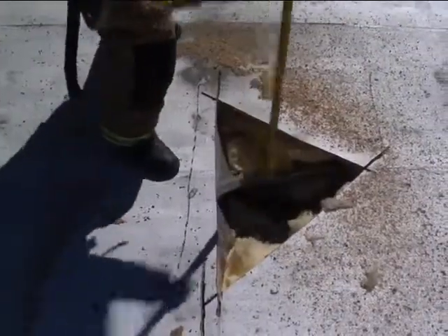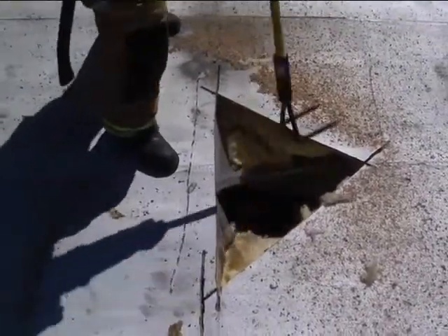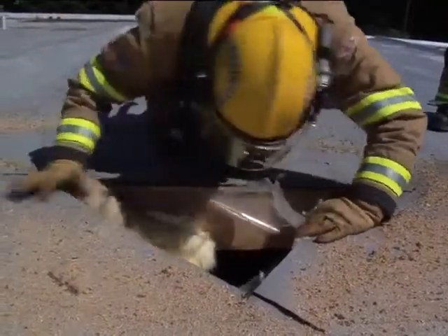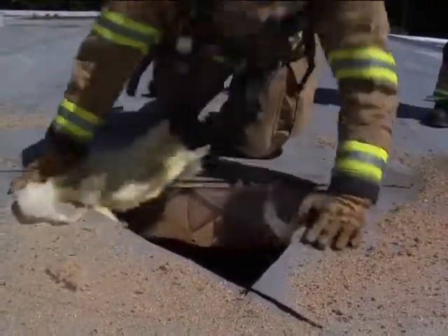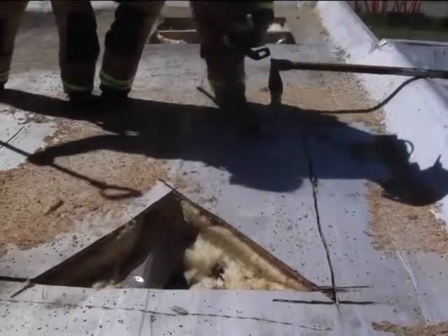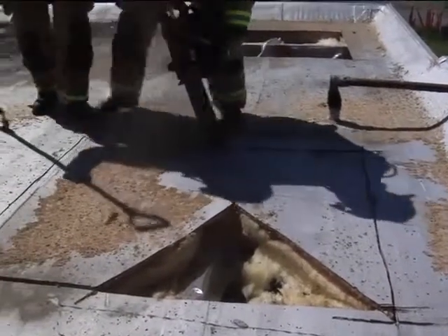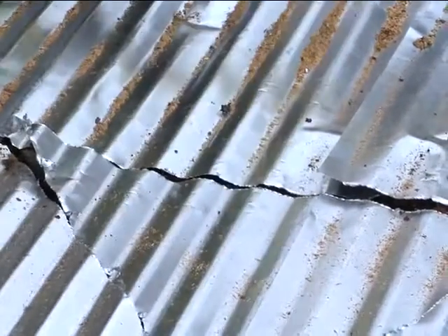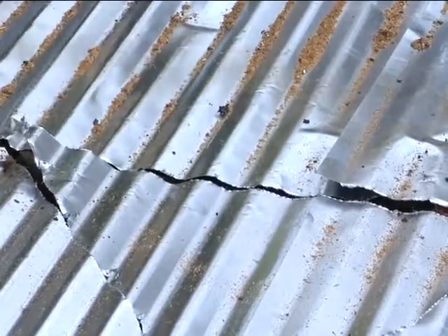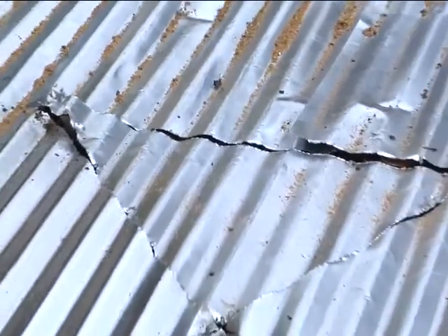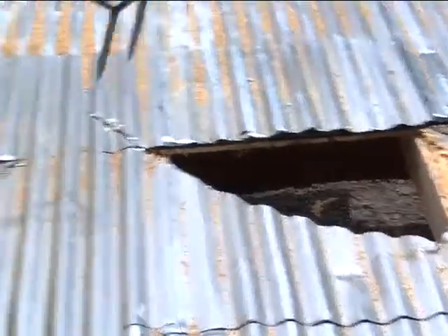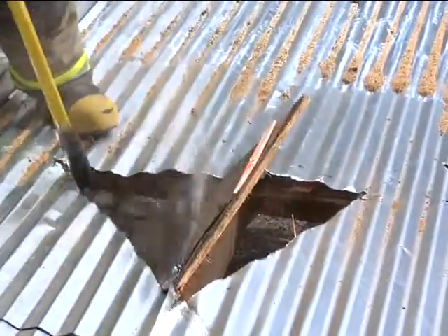The triangular cut can be used in a variety of ways. It can be an inspection hole to determine fire conditions under the roof. It can be expanded to form a rectangular cut. The triangular cut is an effective cut for metal roof decking because it prevents the decking from rolling away as it is cut, creating a dangerous slide. Several triangular cuts may be needed to create adequate ventilation.